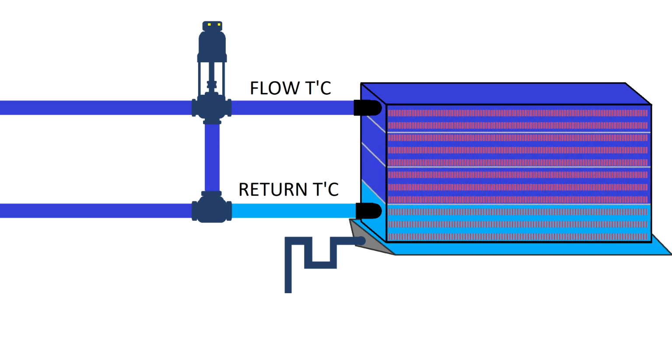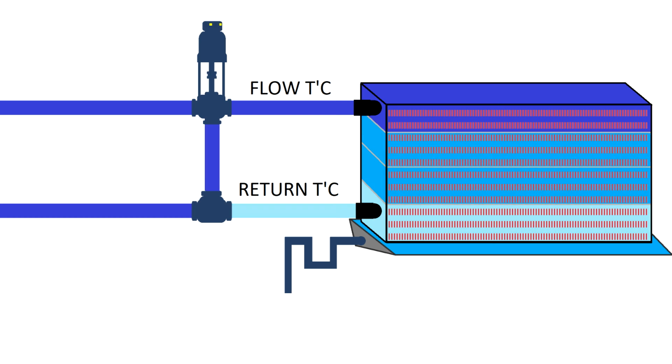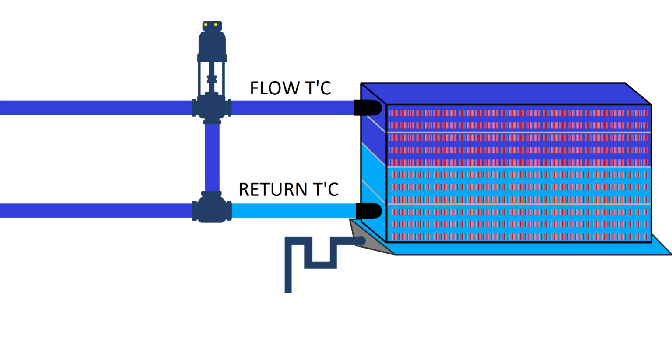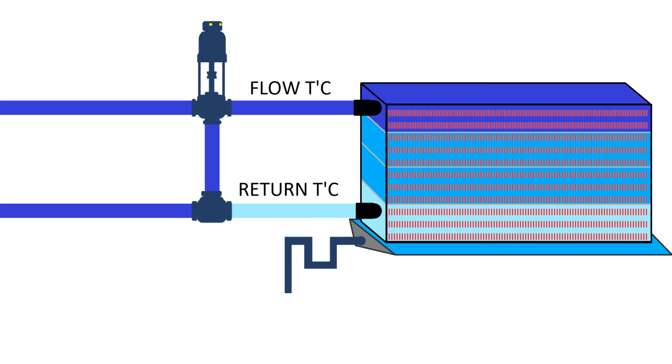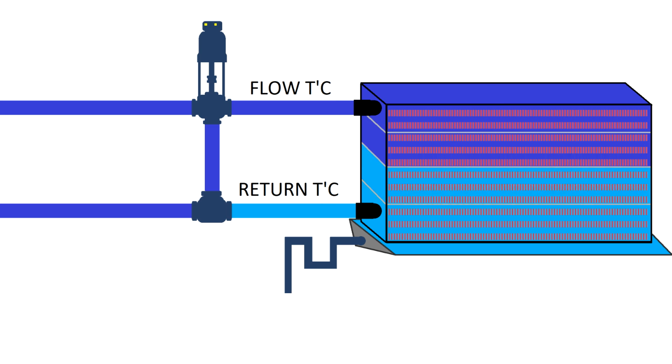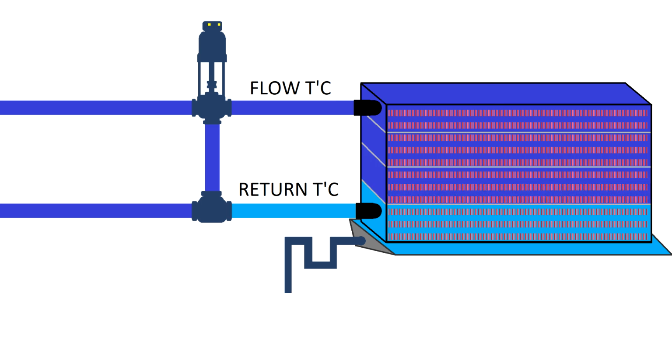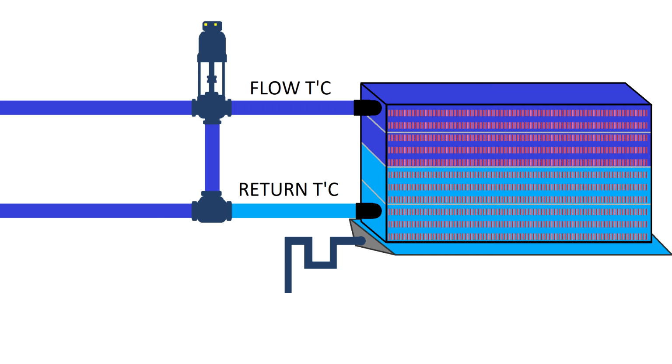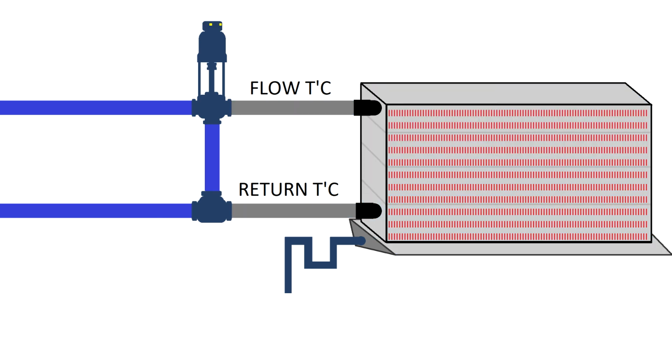So what you will see here, you see the variation of the color on this heat exchanger. The dark blue is very cold. The dehumidification will happen in that area. The rest is getting a little bit warmer, so you might not have dehumidification. The moisture from the air will not condense on that section of the heat exchanger. So that's the way you control dehumidification capabilities.